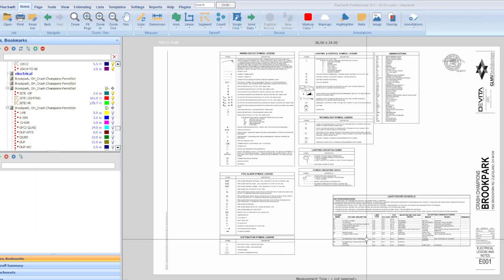The third thing that makes completing an electrical estimate really difficult is determining your wire and conduit totals for branch circuitry for your power plan. Sometimes they'll note it on the construction docs, so you just follow the lines where they lead you, but in a lot of cases they're not shown, especially for the lighting plan.